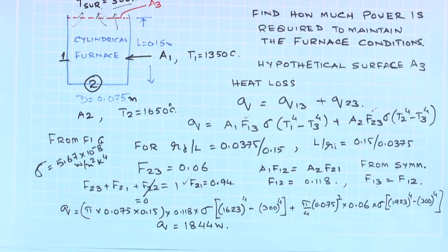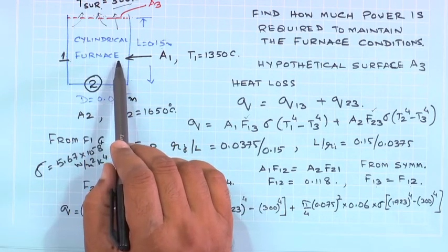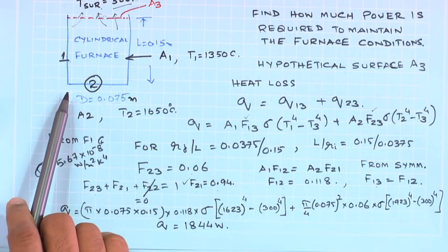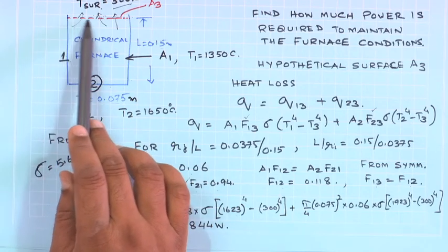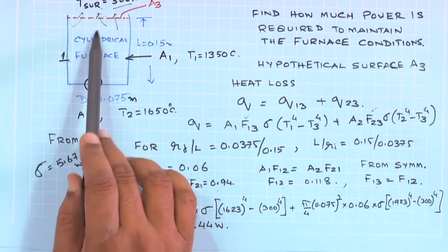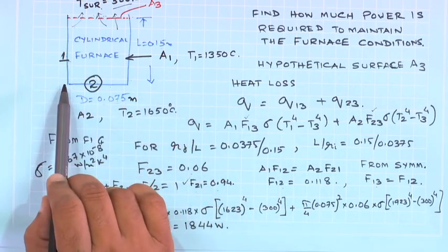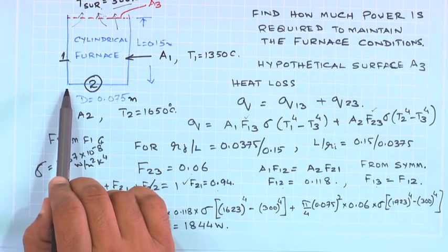So, this is a simple example which shows how much heat is lost by a cylindrical furnace. But if you think of the utility or application of this, it is very significant. Any cylindrical furnace, let us say if this side is not properly insulated, is going to lose some energy, and at this high temperature the mode of exchange of energy is going to be radiation.